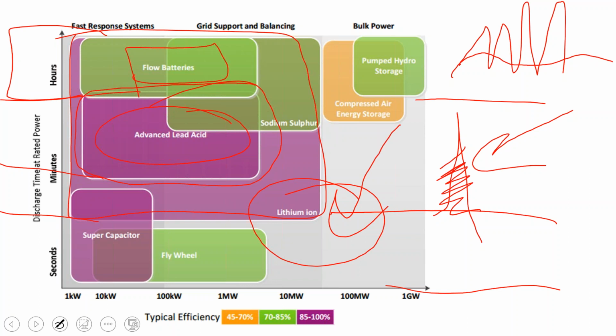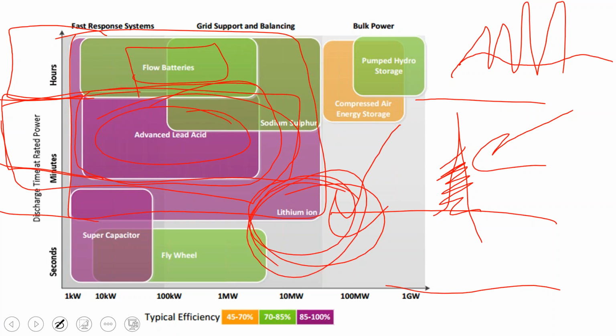And so one way that a solar installer can develop their knowledge is not just doing the solar design, but also speccing out other appliances on behalf of the client to say, if you want to do batteries, don't go with a tankless water heater. Like in an off-grid, it may be better to go with a tank water heater than a tankless, because you could charge the hot water all day and at a constant rate. Whereas with a tankless water heater, instantaneously your building demand surges by 20 kilowatts, at which point you really need a lithium ion for that to be effective.